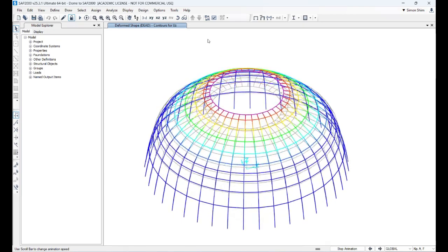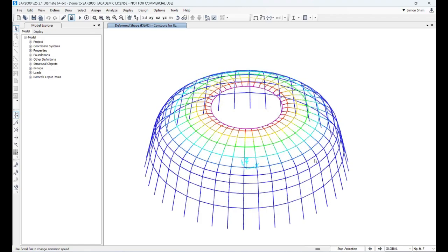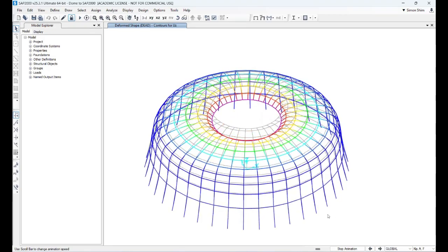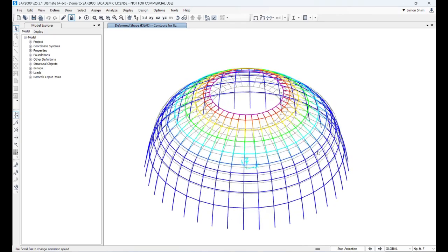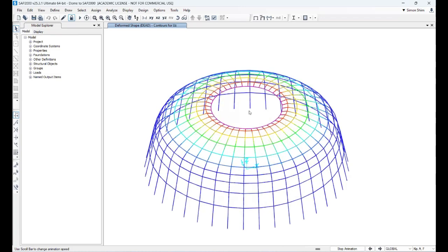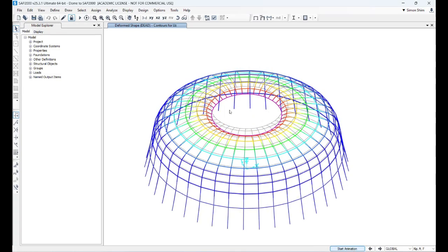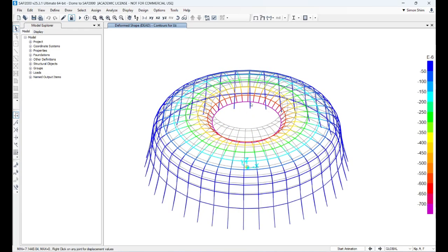So you can see this. I think this geometry is vertically very steep, but where the vertical part reaches horizontally, obviously those areas act more like a cantilever. So I think the top peak here deflects. You can see there's some more deflection. So this is one example, just the sequence I tried to show you. But obviously, structural engineering analysis and design is the next step.